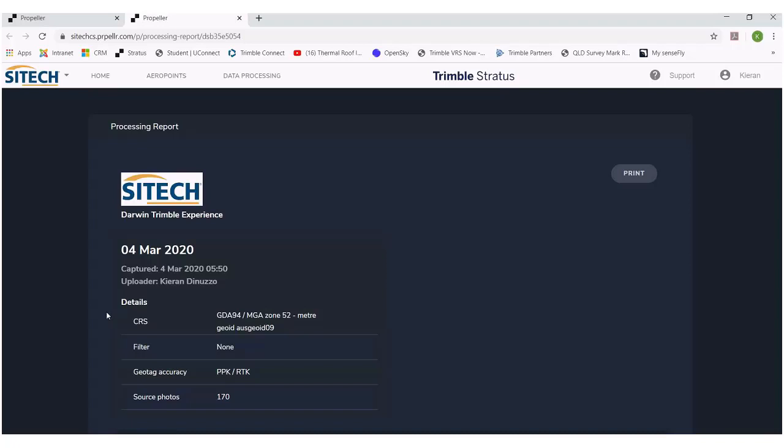So around the boundaries of our site or on permanent roads where we wouldn't expect any height change, they're looking for tolerances to make sure that we haven't done anything strange with our ground control or anything else like that. So we'll have that confidence that the data we're about to look at is accurately processed, which is good.